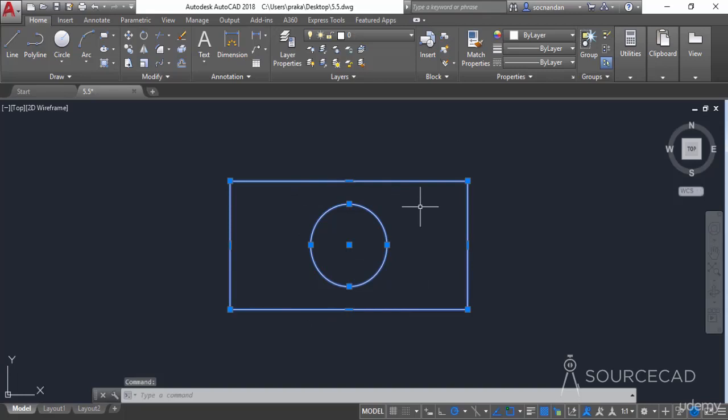Here also, when I select the circle, we have these different grips. Using these grips, we can make multiple modifications in the geometry. For example, here we have this rectangle which is made with a simple polyline, and I'll select it so that the grips are visible. Now go to any of these end grips, and when I hover my cursor there, you'll see these extra options which are available in the menu.